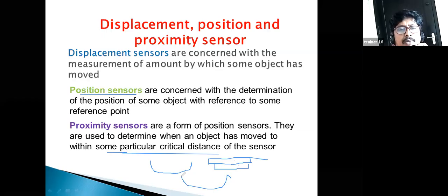That means thermal expansion is there. It will move like this, and then one contact is there. When it touches, automatically the switch is off. Otherwise it will not touch. When the contact is made, it responds and the iron box will turn off.